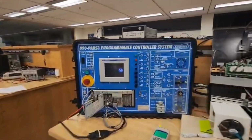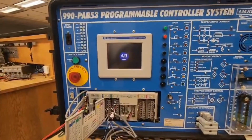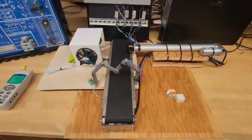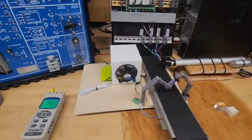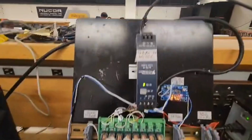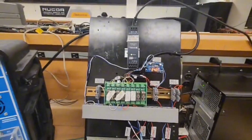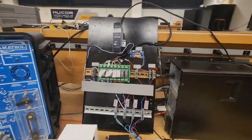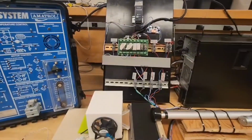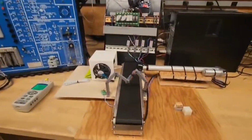So this is the PLC that we are using. We are using CompactLogix L23E QBFC1B, and this is the hardware setup that we have done for our project. Here is our control panel. There you can see we have tagged it all the way through. You can see we have kept signal wires and supply wires separate so that the signal should not be interfered with while traveling from the PLC to the hardware part.